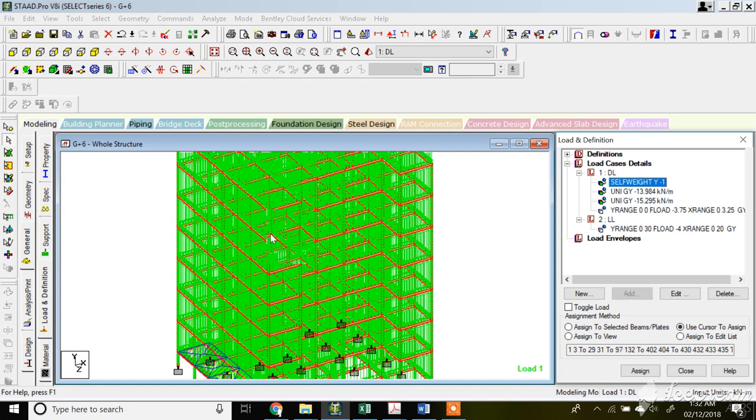So you can do one thing: if you want an optimized design, you can deduct the door and window size and apply the actual loading. You can easily do that for an optimized design. But since this is a tutorial, I've tried to make my design more conservative so that it will be easier for you to design.